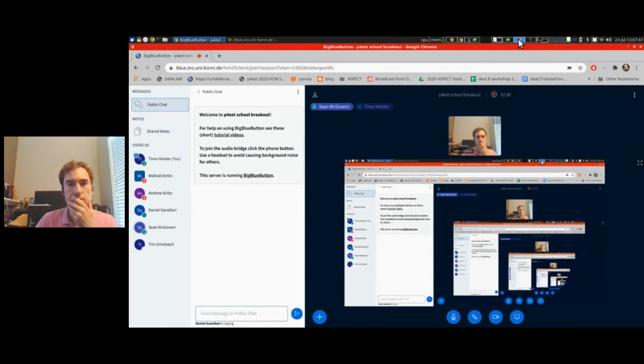So I don't know if this is the right time, but I was just trying to get a better sense of how iterating over cells is the same and how it's different with deal.II and then in p4est directly, because I know that in deal.II, you obviously have a very large user data type thing that you're interested in, and you represent the distributed mesh in a slightly different way, I guess, than p4est does with regard to only storing the leaves. And so, yeah, I guess that's the general area of my question.